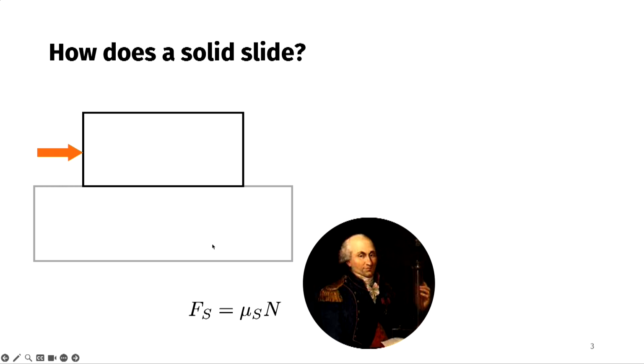If you increase the load being applied from 0 onward in the positive direction towards the right, then the body remains stationary until the load reaches the static friction threshold, at which point it starts moving. This is the classical Coulomb friction model, characterized by this sudden onset of slip at this particular value. This F is given by the friction coefficient times the normal load.